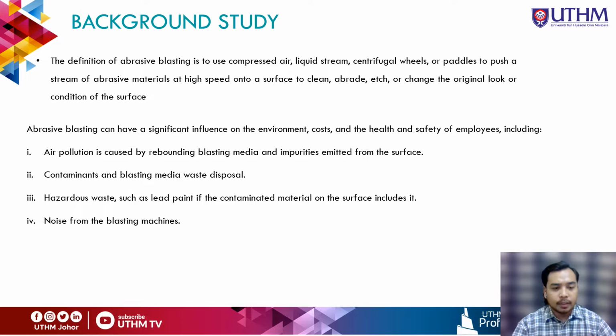For background study, the definition of abrasive blasting is to use compressed air, liquid stream, centrifugal wheels, or pedals to push a stream of abrasive materials at high speed onto a surface to clean, abrade, etch, or change the original look or condition of the surface. Abrasive blasting can have a significant influence on the environment, cost, and the health and safety of employees, including air pollution, contaminants and blasting media waste disposal, hazardous waste, and noise from blasting machines.